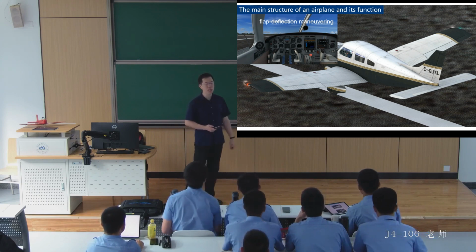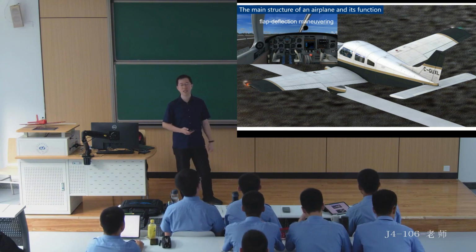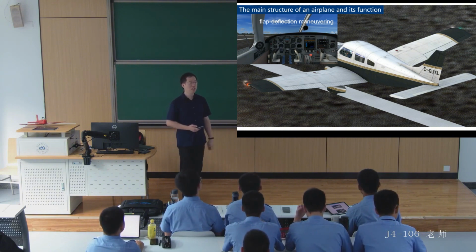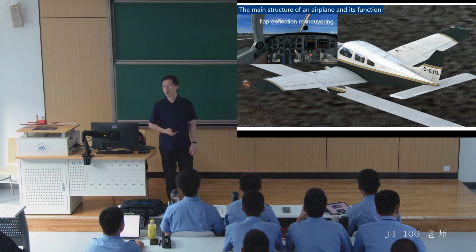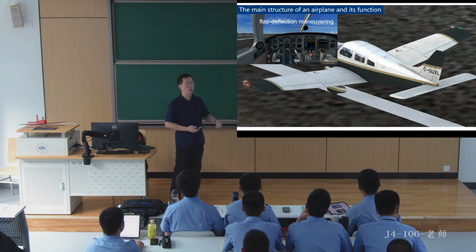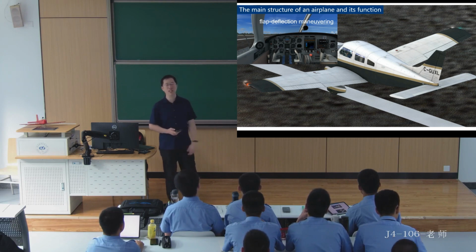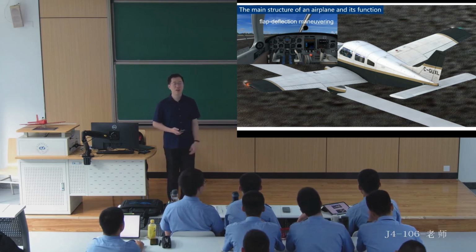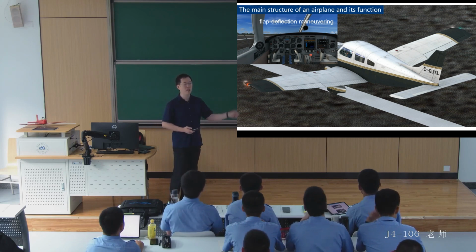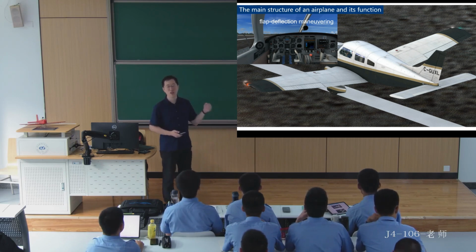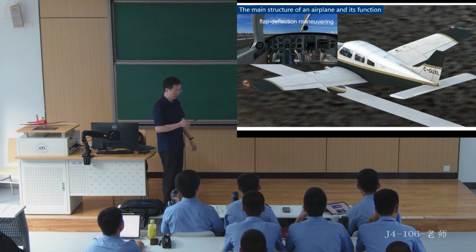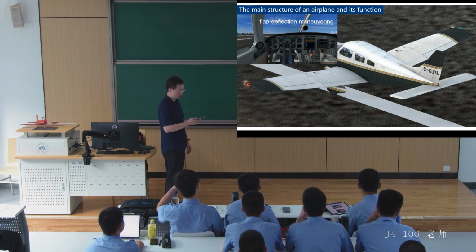Some other aircraft, like the 172, have flaps controlled by electricity. The difference with these is during an emergency landing. If, like in the 172, you turn off the aircraft's power switch too early during an emergency landing, you won't be able to control the flaps. However, with the PA-28 aircraft, you can turn off the power switch early, allowing you to manually operate the flaps to assist. This device is very useful for adjusting the landing point.